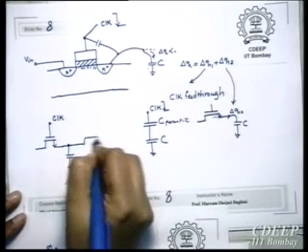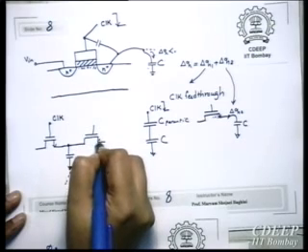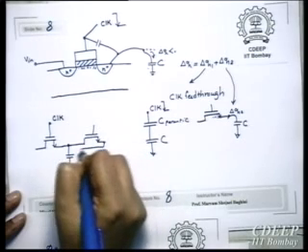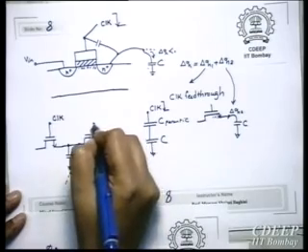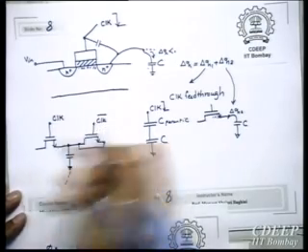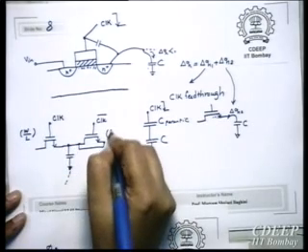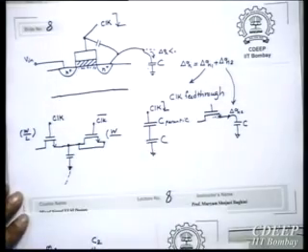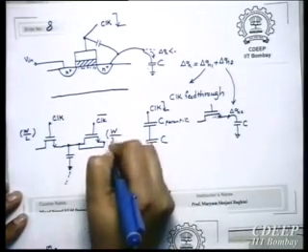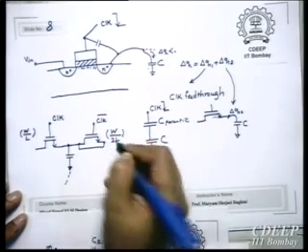Now if you put an additional switch in the form of a dummy switch and connect source and drain, and then give clock bar. Suppose the aspect ratio of this switch is W upon L, the aspect ratio of this switch will be W upon 2L, or in fact W is half.